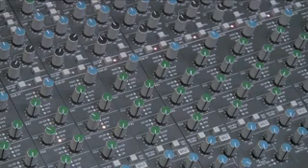Some mixes have dedicated aux sends for the headphone cues. These are called cue sends and are normally stereo. Having stereo cue sends is beneficial because it allows you to further customize the artist's headphone mixes by allowing you to pan your signal left or right.